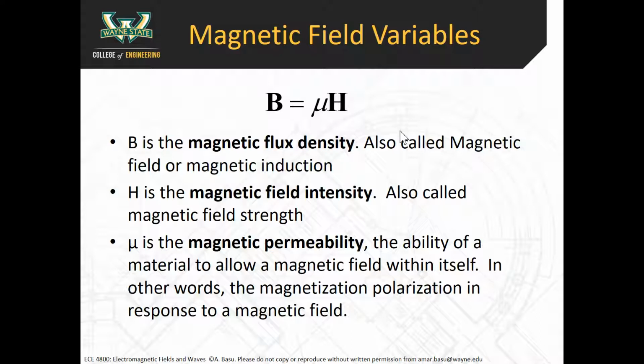So similarly, in short, the dielectric constant tells you that if you have a high dielectric constant, it can sustain higher electric fields, or it generates higher electric fields within the material when these dipoles align. Similarly, with magnetic fields, the higher the magnetic permeability, the larger the magnetic field strength you can sustain, or the larger magnetic field you can have inside the material.